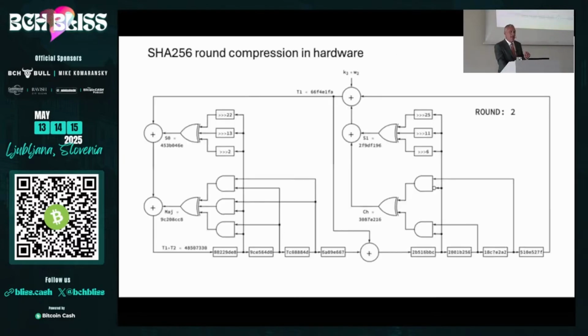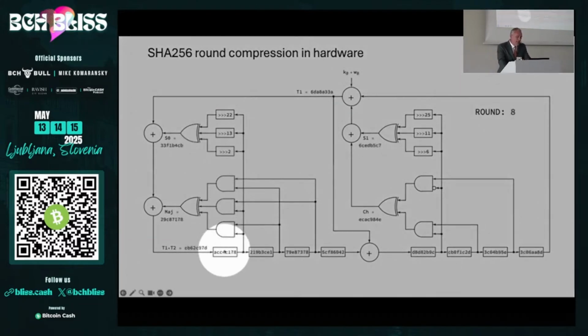Now let's look at solving the problem in software instead. So if I were to implement this in software, all of these registers are going to become variables. And then I'm going to have to AND these 2 registers and save that to a temporary variable, and some more variables, and some more variables. Save all those and XOR them all together, do a bunch of summing, and basically build up the feedback terms instruction by instruction, and that's going to take many clock cycles.